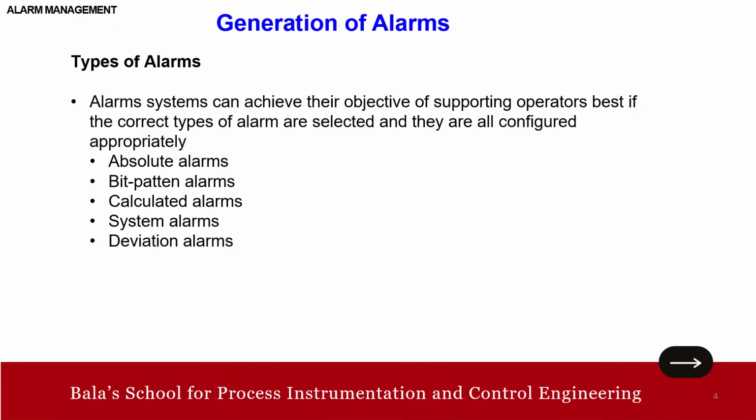Then the discrepancy alarm. Discrepancy, as you know, is generated by comparing an expected process state against the actual process state. Maybe you take a case of an actuator. This requires some model of the expected movement of the actuator in response to the commands from the operator. For example, the actuator should always show the correct state, open or close, within 10 seconds of the command being sent. A good discrepancy alarm check will identify faults such as a stuck actuator or actuator runaway. So this is about the discrepancy alarm.